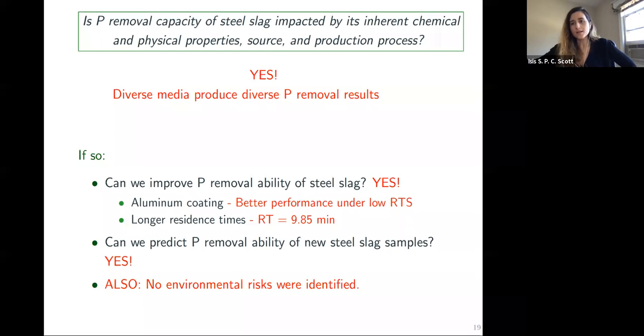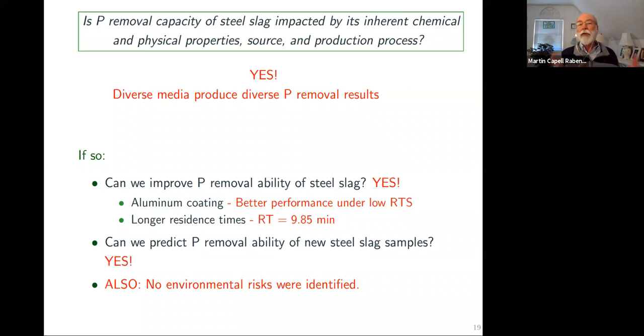We would treat that with calcium chloride. So we would have the dissolved phosphorus precipitated on the bottom, and then we can dispose the solution to the closest ditch, because it won't have a higher alkalinity, and the pH was okay. We tested that as well. It was also in the circumneutral range, and that's it. So you can actually precipitate the phosphorus into a solid phase, so you don't have this huge volume of material to deal with.